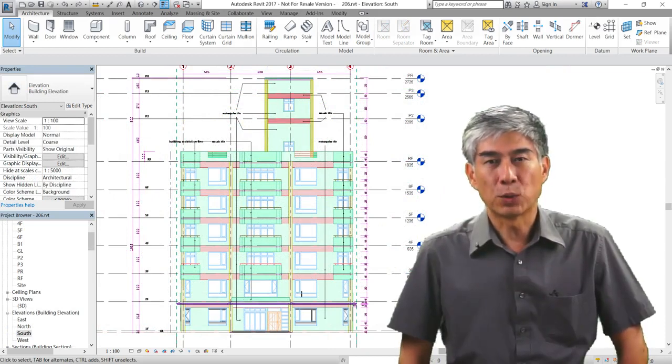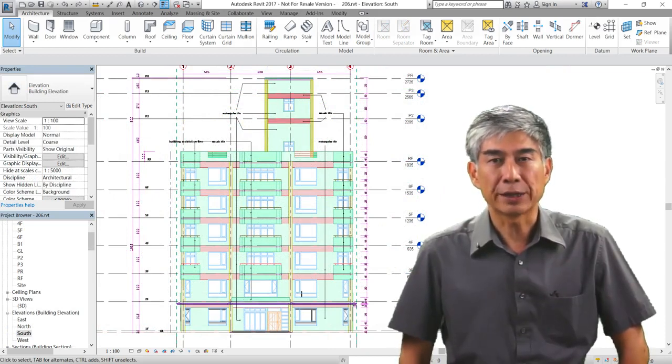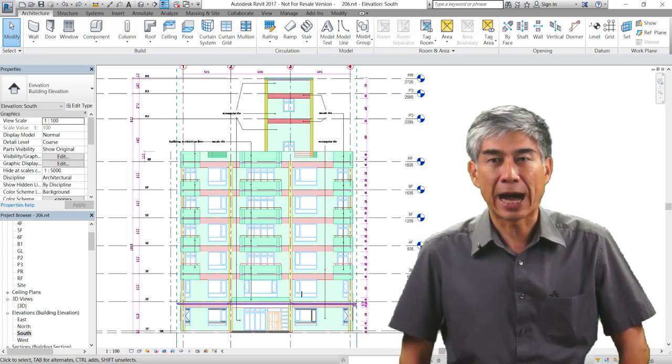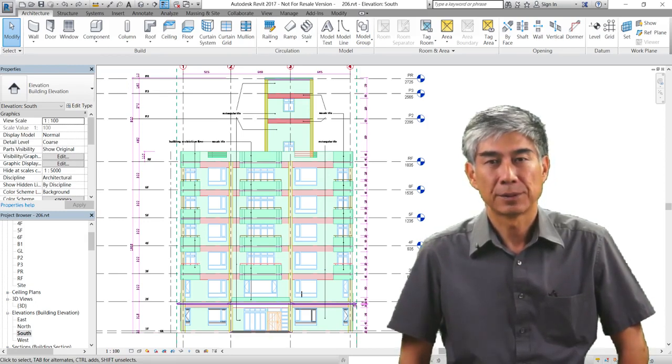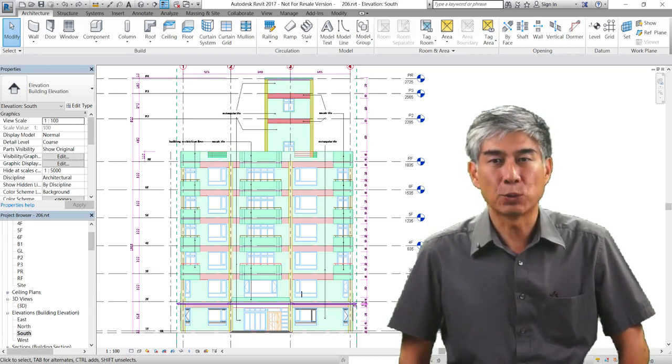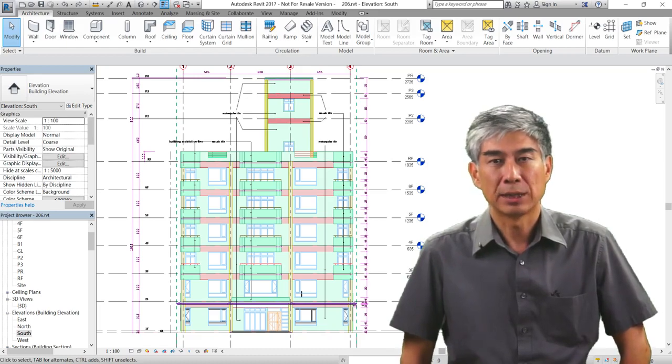For the exterior walls, because the thickness of tile does not affect the space of other elements, we may use the pen tool to model the tiles. The process of painting the exterior walls is the same as that of painting the interior walls. We have two paint types for tiles on the exterior walls.